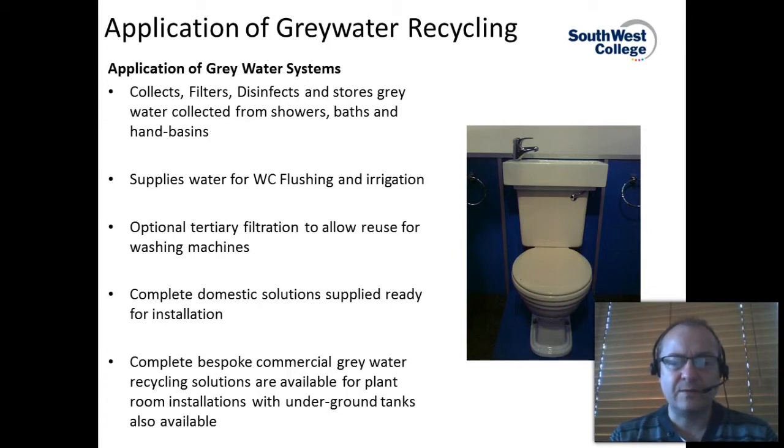Complete bespoke commercial greywater recycling systems, larger scale systems, are also available for plant rooms, and these come with large underground tanks that are also available. Large scale ones would be common in the Middle East, where they'll reuse the water from showers and hand washing in applications like hotels, where they'll then use it for flushing the toilets of the hotel.